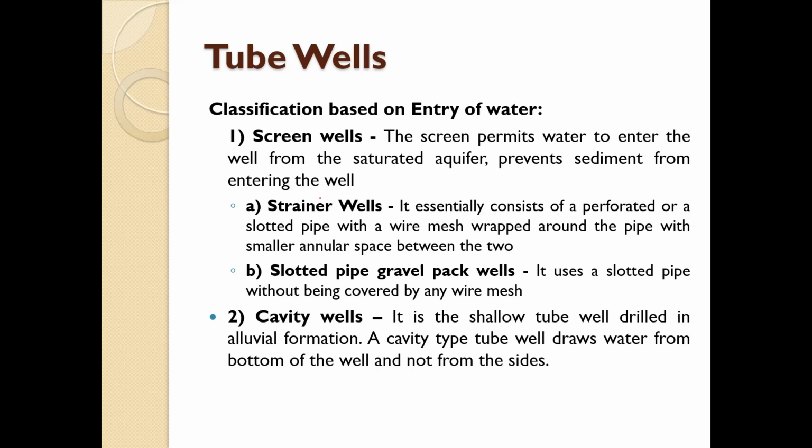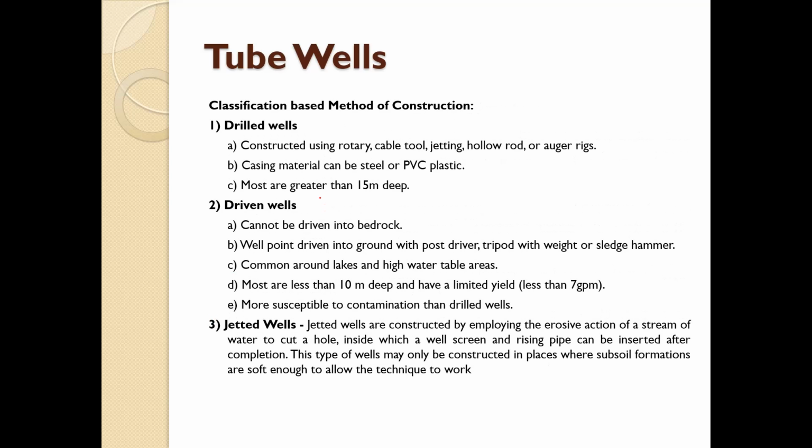Then the cavity wells. It is a shallow tube well drilled in the alluvial formation. A cavity type tube well draws water from the bottom of the well and not from the soil, as we have discussed. Then the classification based on the method of construction.